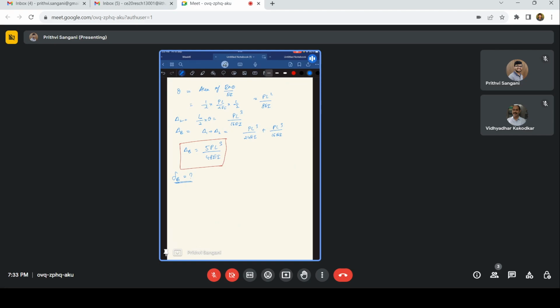So why do we use kinematic indeterminacy and static indeterminacy? Where are we going to use such things? I think we need to wait some more time to actually understand the stiffness method. Usually we use this to formulate the stiffness matrix method. All the codes written for structural analysis, like STAAD, are actually based on the stiffness matrix method. Like we have formulated a basic flexibility matrix, in a similar fashion we'll also develop a stiffness matrix.